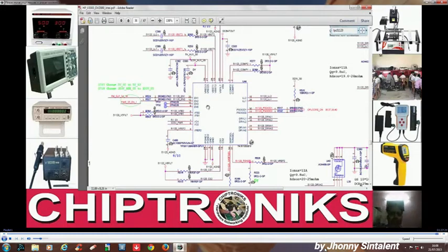These differences are basically due to differences in power sequencing, due to the use of ICH in DV2000, and due to the use of PCH in Lenovo i3 Y470. And we'll discuss all about this switching power sequence in the next class before we start IO controller. So I think for now we are pretty clear about the switching regulators, and in the next class we're going to cover the IO, and before that we'll have the ACPI, understanding the power sequence. Thank you.